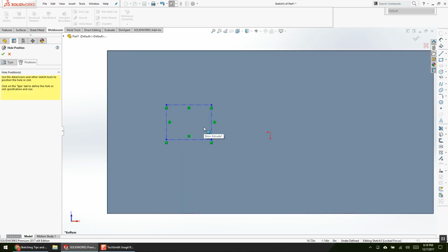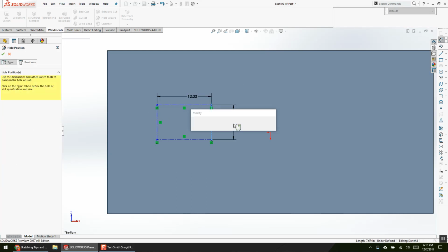Okay, so the bolt hole pattern for my legs is a square bolt hole pattern. So in no way, shape, or form do we want to put 2 dimensions on here, because I have now doubled my liability. Right? If I say 12 inches by 12 inches, my boss comes to me and says, here's a new leg pattern, and they're 14 by 14, 14 square. I now have 2 dimensions that I'm liable for. Right? So I don't want that.